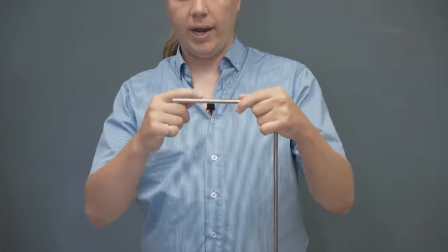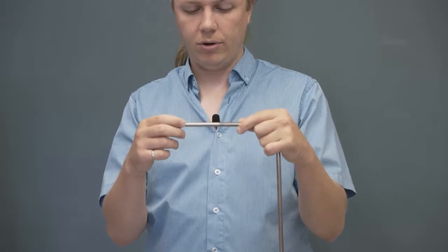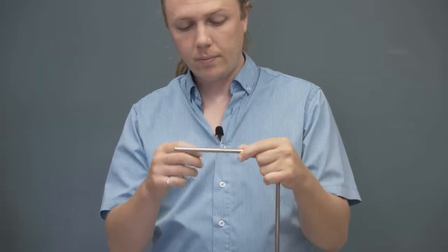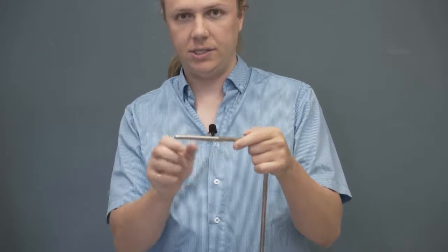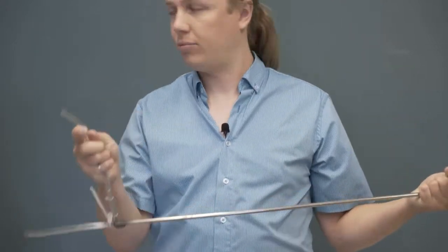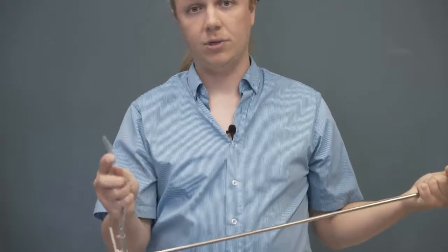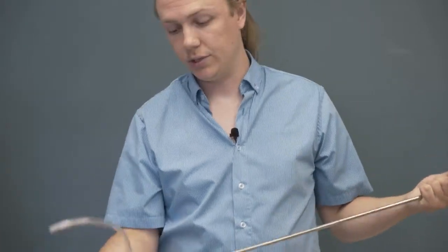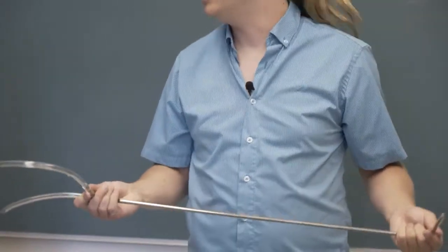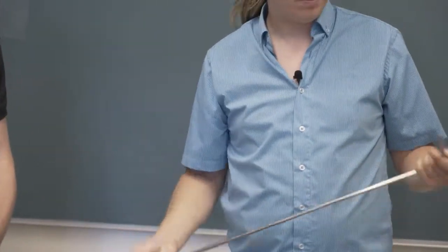We also have a ring around the perimeter of the probe here that measures the static pressure of the flow. And that ring feeds into this larger tube, and we can sense the static pressure up here through a second tube down here. So we can hook these to transducers or to water manometers or a lot of different ways to measure pressure once we have it.